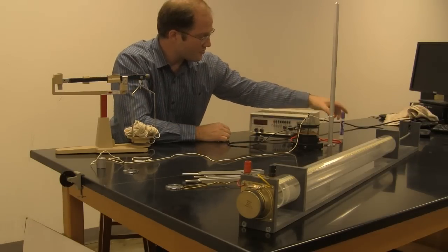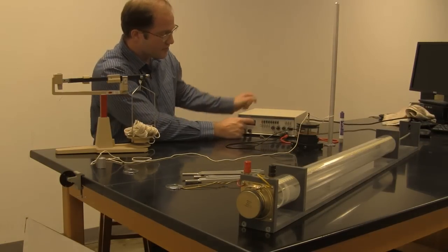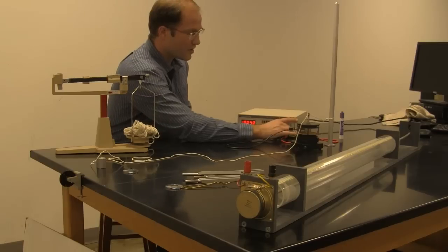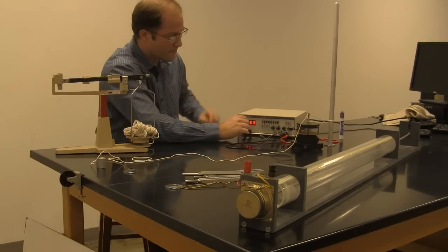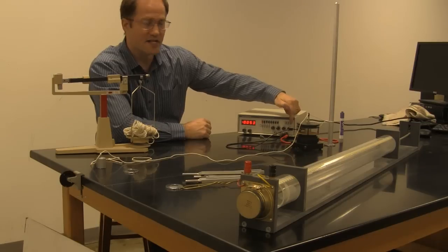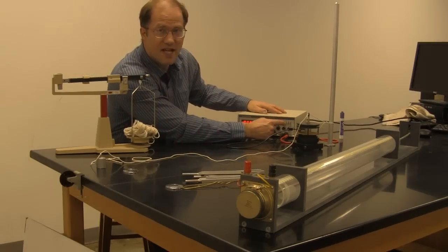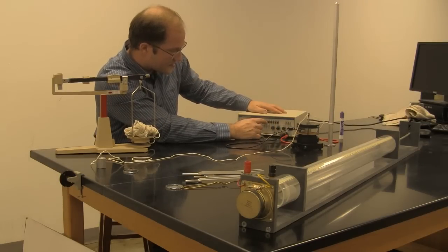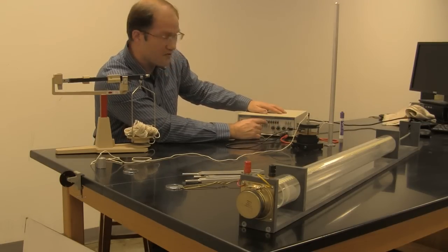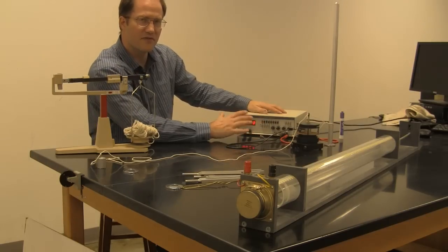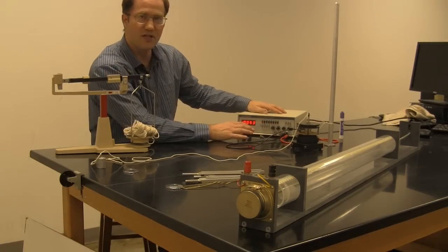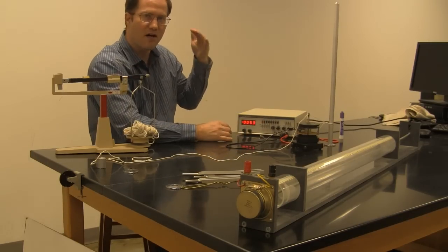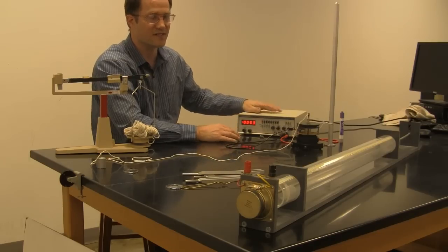Now the function generator should be turned on. We're going to have its volume all the way up. The gray buttons here on the right side of it should be set to sine wave. And the selection for frequency should be set on 50. We're going to vary around 50 hertz. I don't think we should go up as far as 100. We'll be able to audibly hear the tone and the room will get noisy.